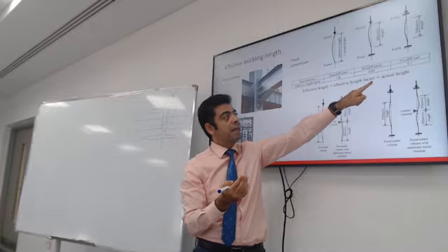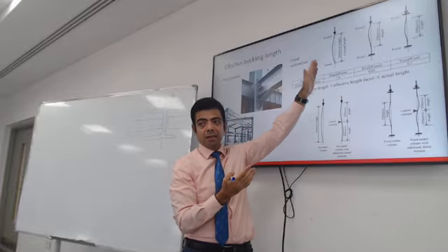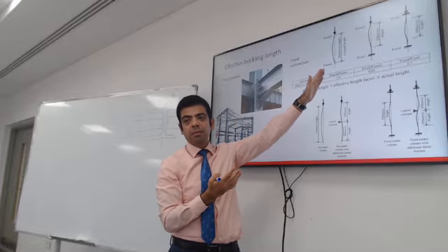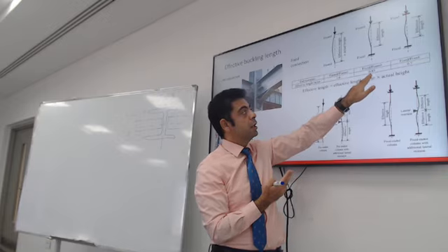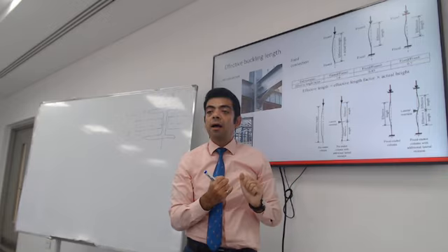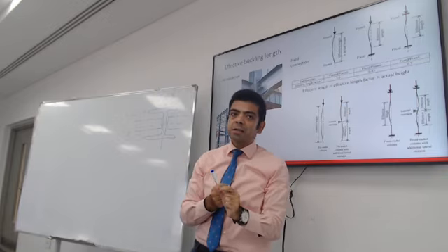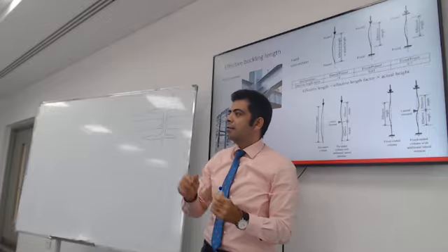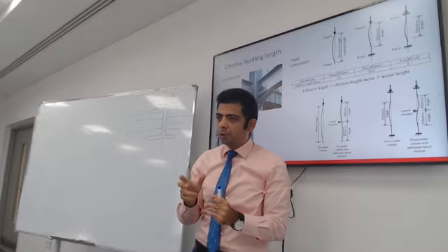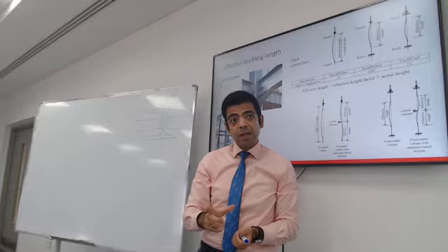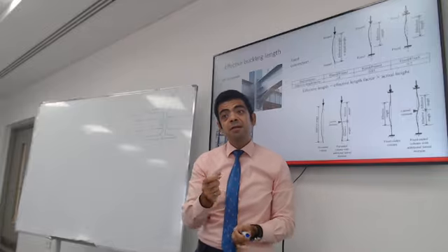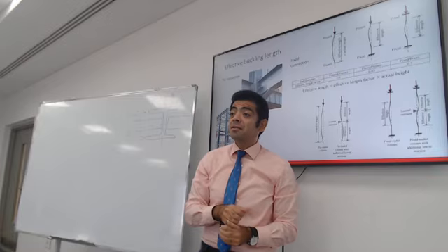That means you take the actual height as the buckling length. If your column is fixed, you can reduce the height, which can help your section. So let's say you have a column and you're struggling to get it to take the load. If you change the connection to fixed, there is a chance that you can increase the capacity of the column.